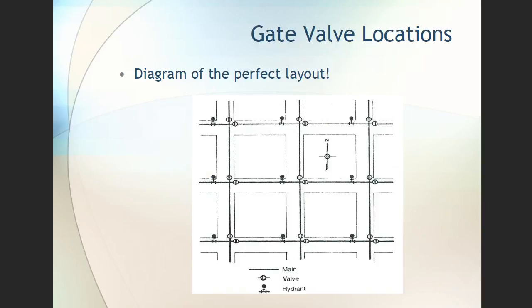Gate valve location. Gate valves are an operator's best friend. The reason why is because you're going to be able to isolate little specific sections. And by isolating those sections, if you have to work on that section, you're not shutting the whole system down.